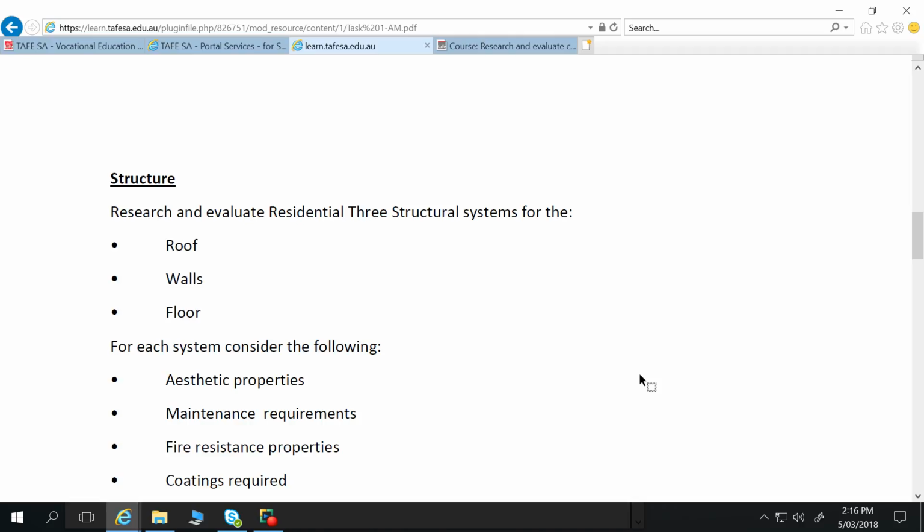When you say structural, are you talking actually about the cladding, or are you actually talking about the framework? The framework, so the underlying structure. So this assignment makes that distinction between cladding, which is the external skin, either cladding for the roof or cladding for the walls, and structure. In some scenarios that can be the same thing. For solid masonry construction, our structure is also our cladding. So when we use cavity brick construction or even double brick construction, that is both our cladding and our structure.